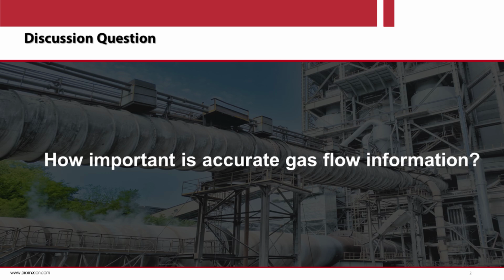Well, the objective of every plant is to produce a very reactive clinker. Reactive clinker is basically the fundamental part of our product. So that means getting the right heat profile in the kiln, the right heat transfer into the clinker, not too much, not too little. And most plants these days are using pre-calciners, so we have combustion in two spots. We need the combustion to drive the reactions that we need.